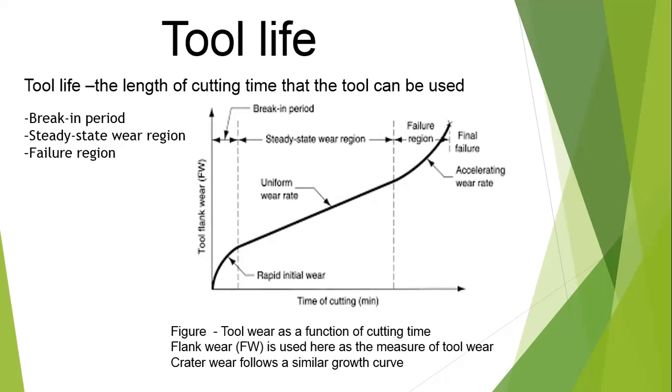At the initial stage, the break-in period, tool wear is high. After some period, the tool wear is linear. Then after some time of operation, the failure region occurs, and there is a break of the tool.